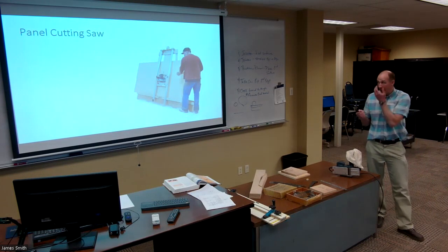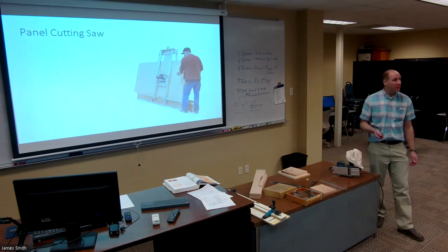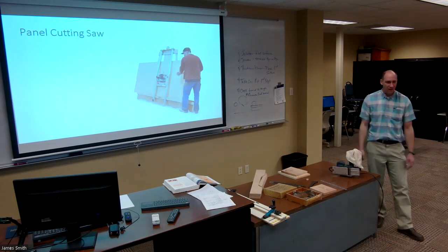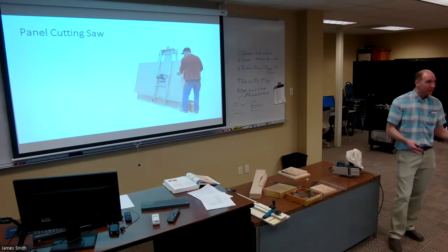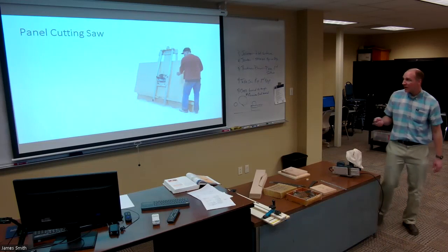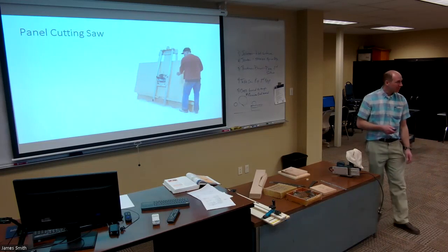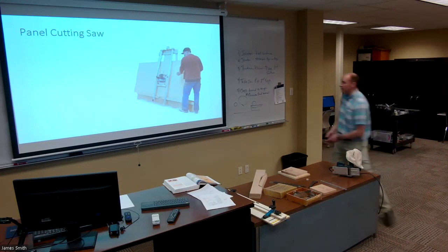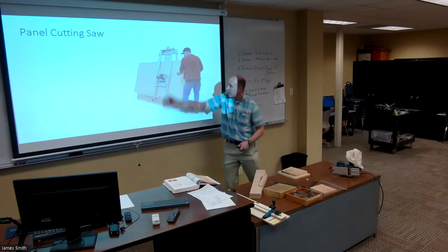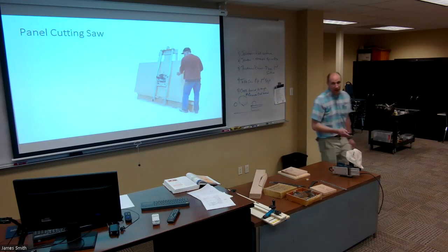This shows a panel cutting saw. These are really good when dealing with plywood, because plywood is really wide and long and awkward, and oftentimes it's really challenging to get 2 people in sync when you're trying to rip or cross cut, and so sometimes it's just better to cut it on a panel saw. So you can hold the board in place, and then it has this track where you can just bring that saw down and cut through the plywood.